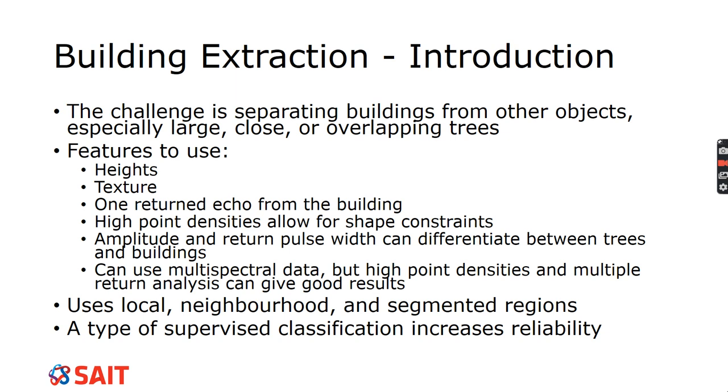You can also have other features like power poles. There are radio towers. Some people put towers up in their yards. That can also cause an issue with extracting your buildings. So there's lots of stuff that does happen in people's yards, but trees are the biggest one. So there are different ways that we can try to extract those buildings from underneath those trees, or even just extract the buildings from a DEM that is clean without any trees overlapping.